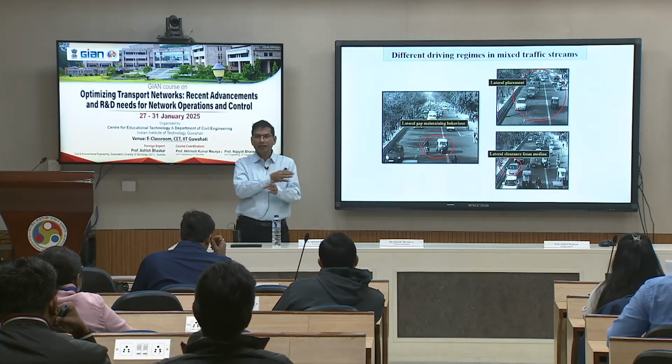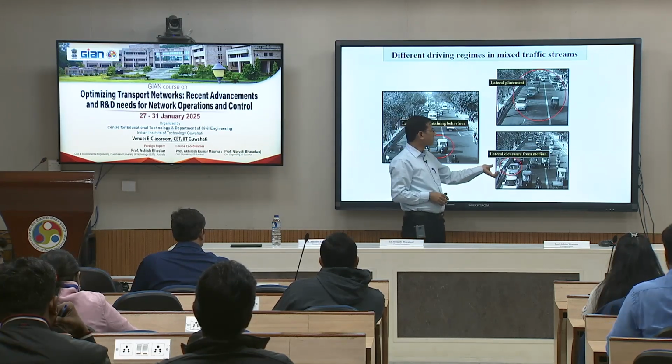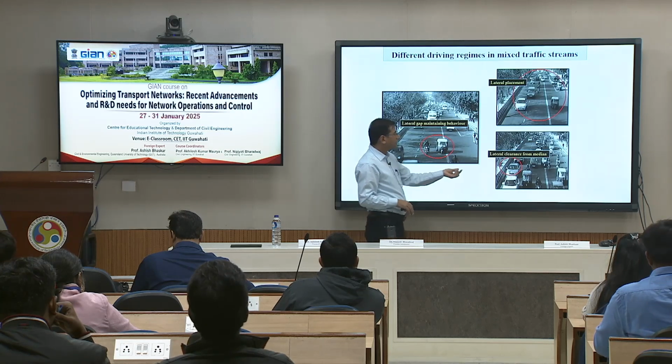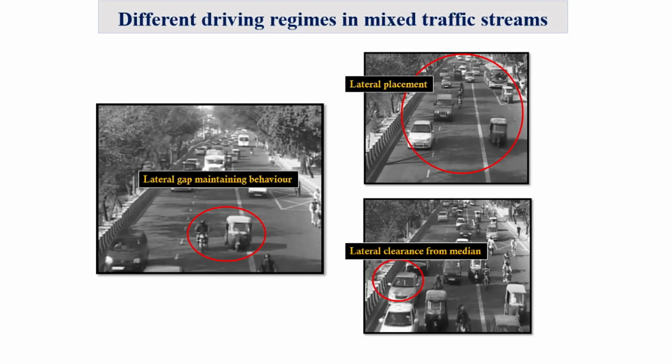Depending upon that, in order to prevent pedestrians from crossing the road, sometimes you may see that the height is close to 1 meter, which significantly impacts how much clearance you are going to maintain. If it is just a standard 20 centimeter height, you might be moving very close. But if it becomes 1 meter height, you might be maintaining a 1 or 2 feet gap. So how is this gap maintained, and what are the factors which govern it?